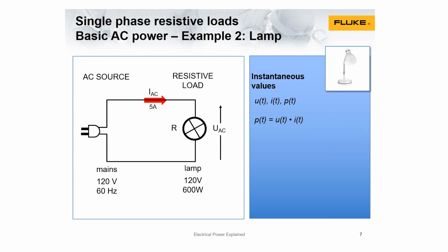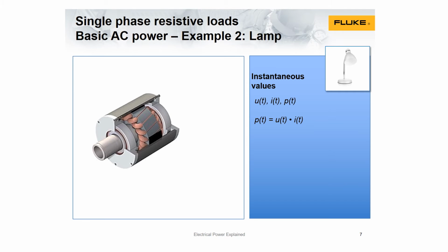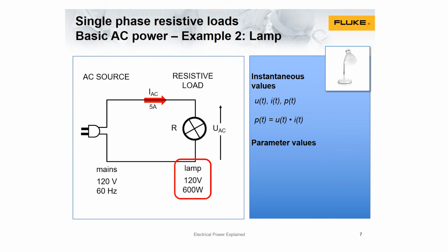Instantaneous voltage, current, and power. With AC, the voltage, and so the current and power, vary over time. The most general statement is that instantaneous power, P(t), equals U(t) times I(t) at any time. Rotating generators have traditionally generated the voltage that supplies the current. When something rotates, the height of each point on the circumference varies as a sine wave. So, a generator produces a sine wave voltage.